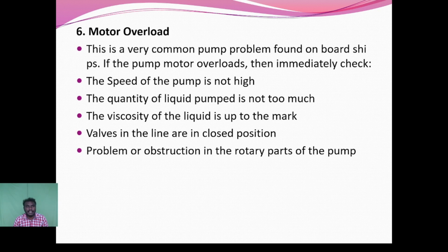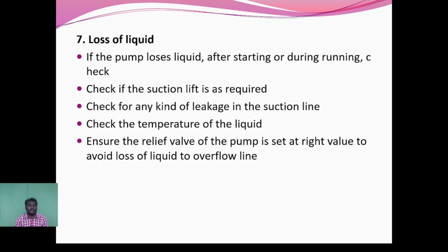This is a very common pump problem found onboard ships. If the pump motor overloads, check that the speed of the pump is not too high, the quantity of the liquid pumped is not too much, and the viscosity of the liquid is up to the marked level. Check that valves in the lines are not in the closed position, and check for obstruction in the rotary parts of the pump.